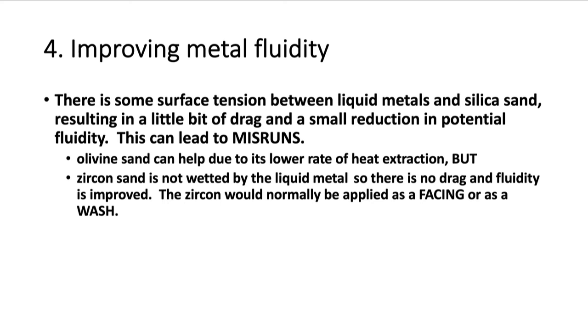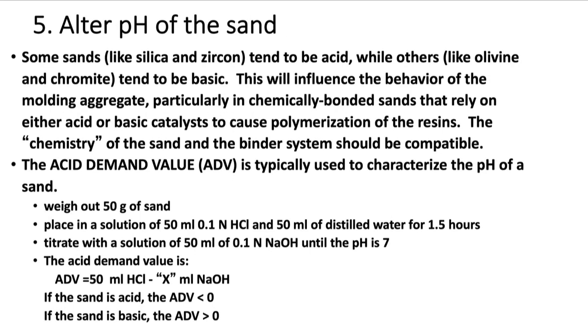It's hard to reclaim. One thing you can do with chromite sand is you can reclaim it magnetically, but you can't do that with zircon sand. Okay, so that's the fluidity of the metal. The pH of the sand. Again, if you put the sand in water, it will either act like an acid or a base.